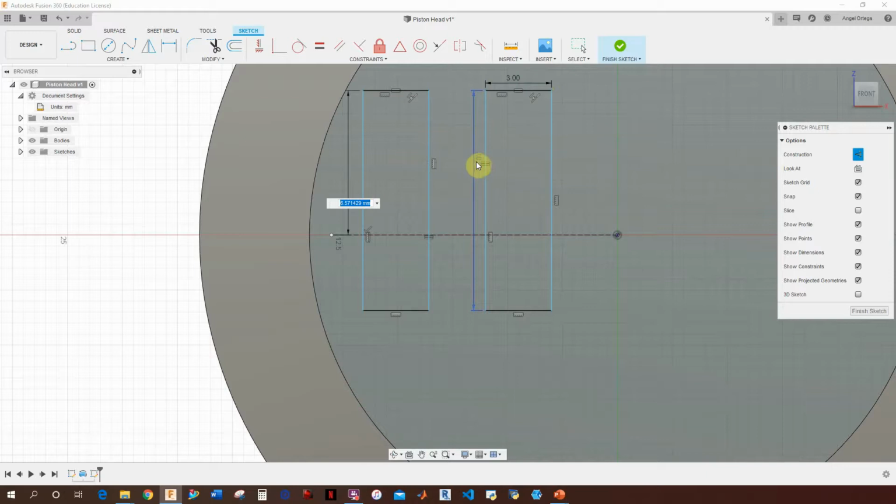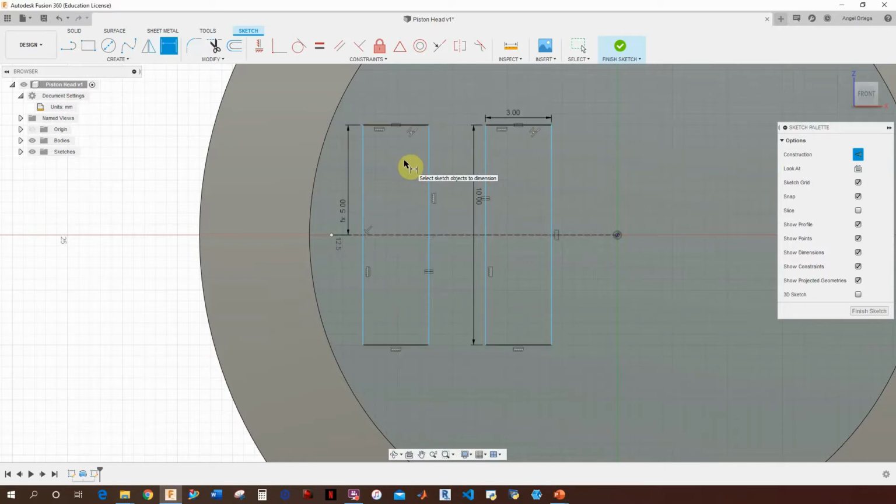So if you hover about the 10, you'll see that new text box open up. So D11, that's the variable for this distance here. And then all we need to do here is for my new dimension is type D11 divided by 2, because half of it has to go on the top, the other half has to be on the bottom, right? So now this one, by doing it this way, we just created a function.